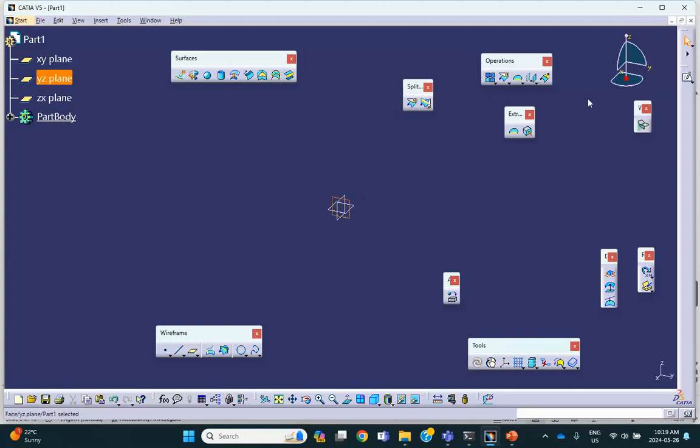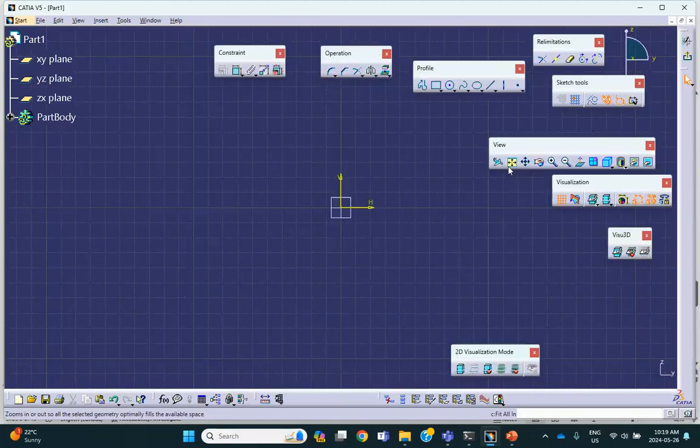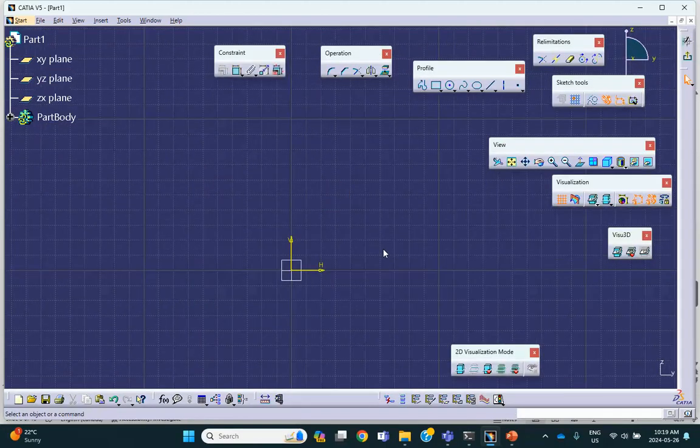All right, so there we are. I'm using the wireframe and surface design in order to draw that. So let me draw my L. This is a 30-degree sector, and half the height is already done with a cut.